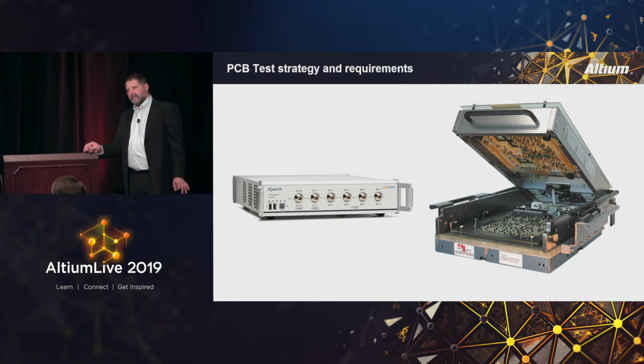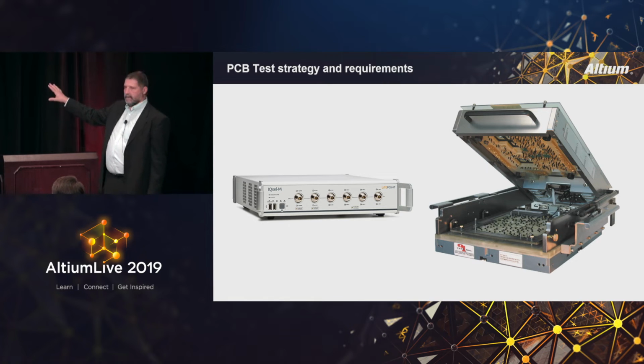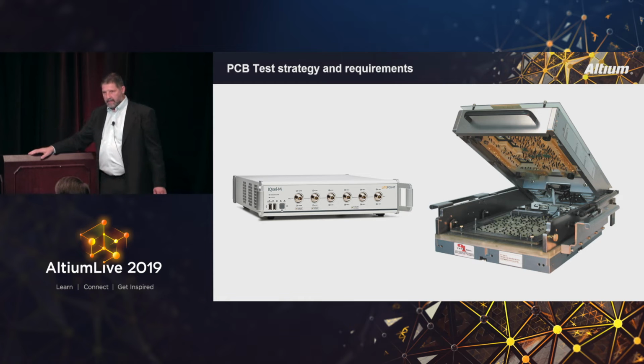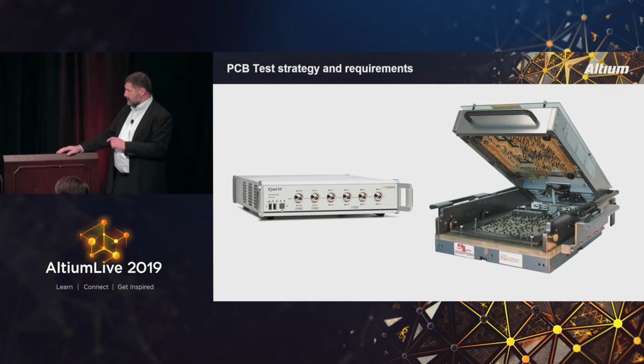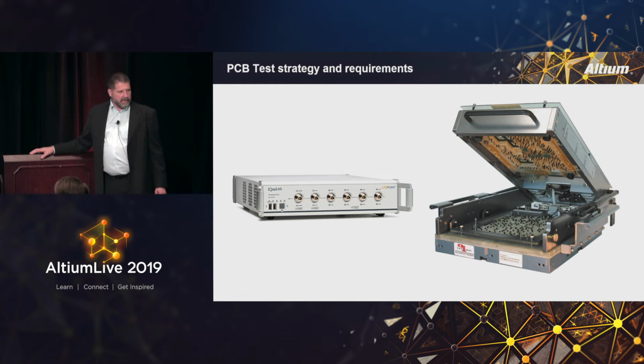And in high volume manufacturing, they will need to replace that expensive part. These fixtures might cost anywhere from $5,000 to $30,000, maybe $40,000, depending on how large the board is and how many connections. And they might need multiples. So by giving a good pin-to-pin spacing, you'll save quite a bit of money.